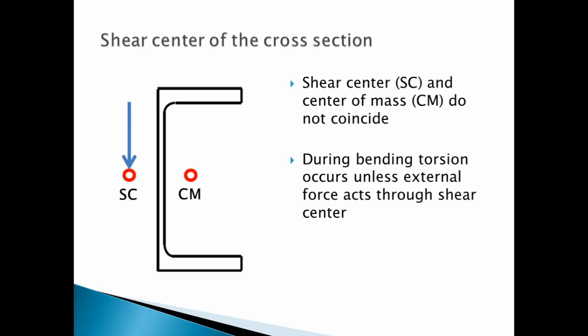That's why I will be modeling the force through the shear center, and I will be adding additional shell elements so that our force goes through the shear center and we will have only bending. If you want to do an eccentrically loaded channel section, it's much easier. You just put the force on the web or on the flange.